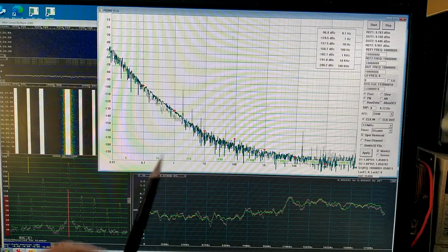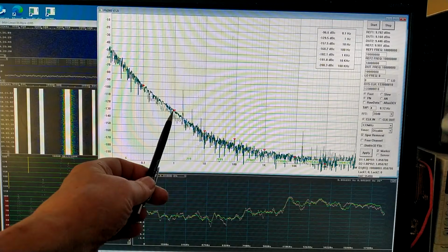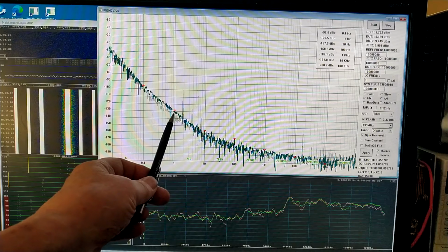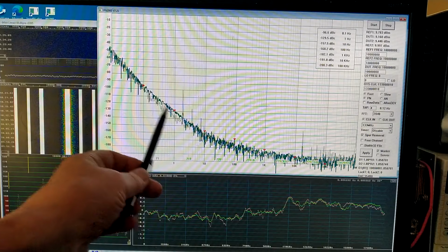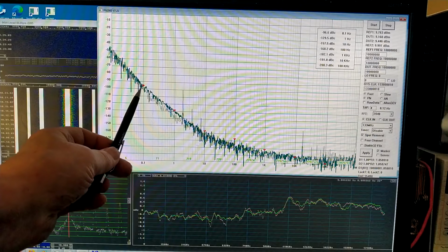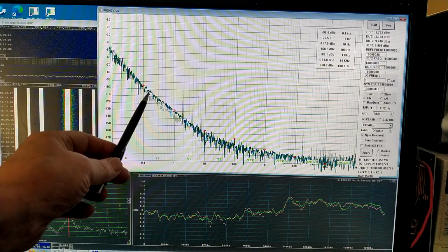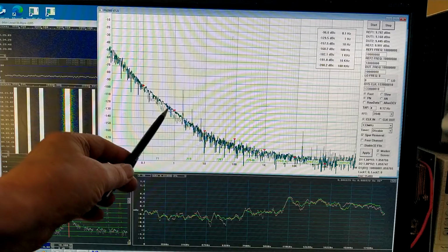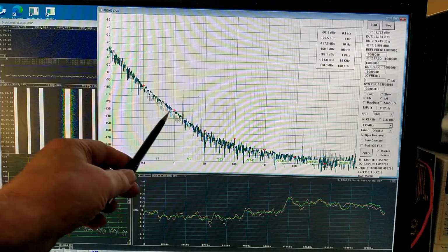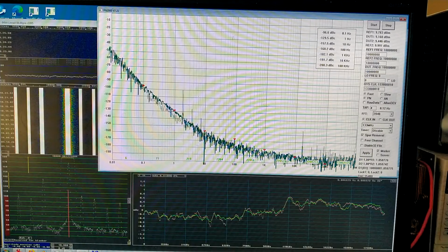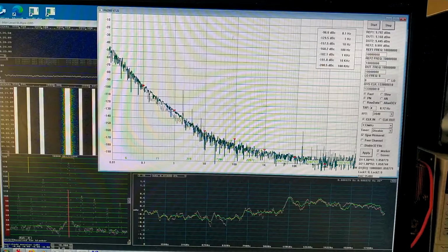At 1 Hz offset, I can clearly see that the noise floor has increased. Now about minus 129. And at 0.1 it is not as bad, but I think it has increased a little also. And you can see clearly the reported noise values are well above the imaginary part here. This could be because of an interference event, or it could be because of an extreme temperature sensitivity.